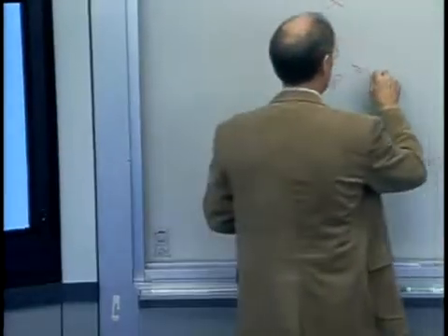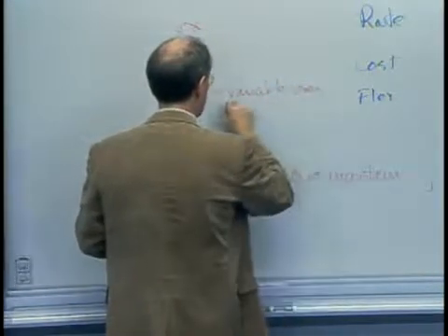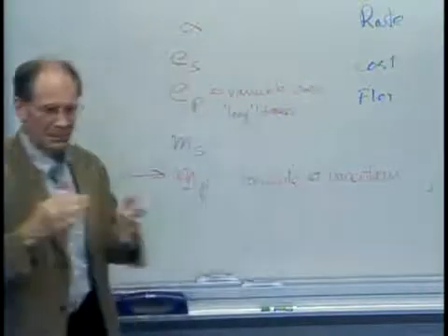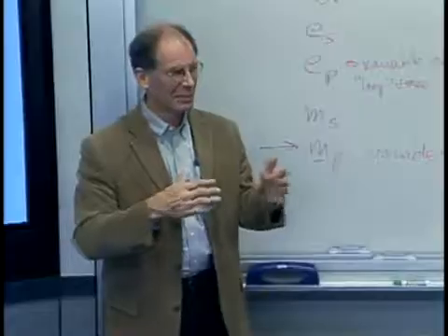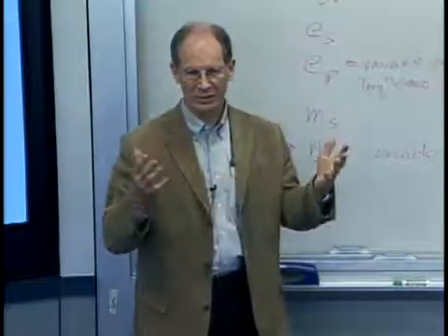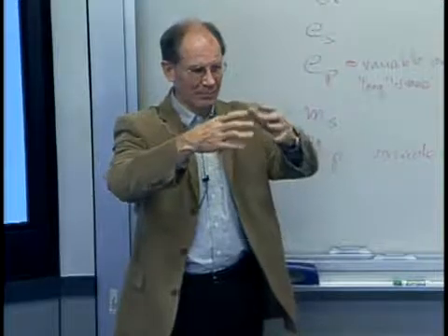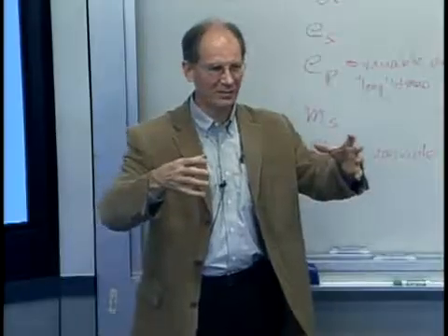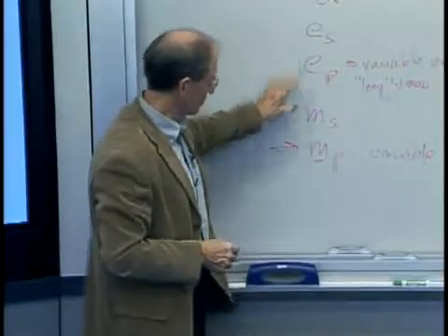So this can be variable over many cases, long times. That's a maintenance issue as much as anything else. But again, it's within a question of how good the machine is. If you build a machine with very sloppy bearings, a sloppy bearing is basically a noise generator, right? You just don't know where things are. If you build a machine that is supposed to distribute a vapor and it's got some sort of vapor handling system that's supposed to distribute it evenly, but it clogs easily or it just wasn't designed properly, then you've got bad properties. Could cause variability.